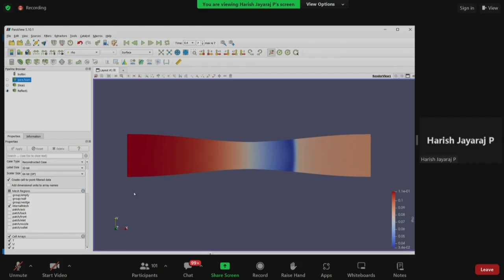While you are creating the blockMesh itself, you can give the name, like how we did in this case. We have given the name while making the mesh. And you can also define what type of boundary it is, and we can simulate it. And we can use the same thing as an empty boundary condition, that the type.